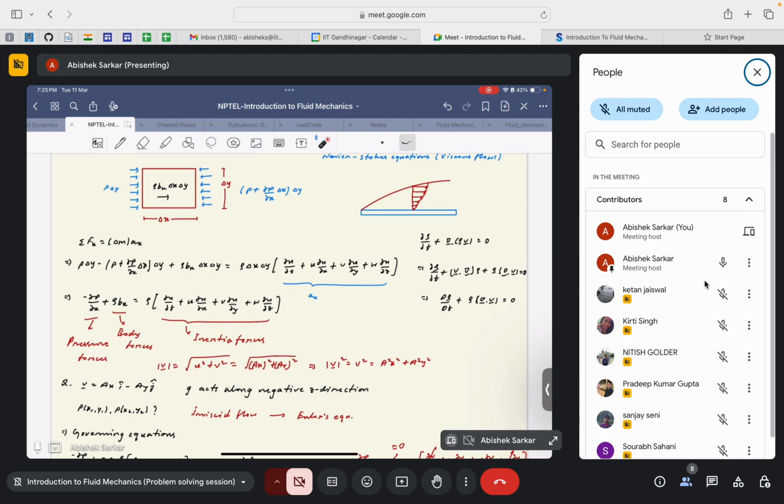So with that idea in mind, when density is a variable, then we have to take one other equation, that is the equation of state, P is equal to rho RT. So we need to again take the help of this equation to find an expression for density, and then solve Euler's equation of motion accordingly. That is what I was eventually saying.